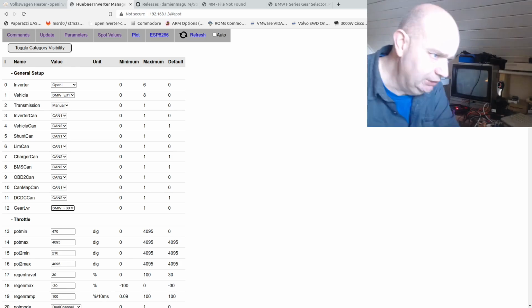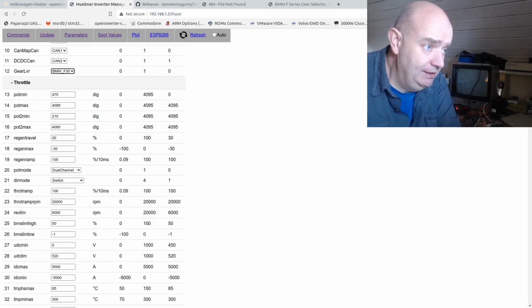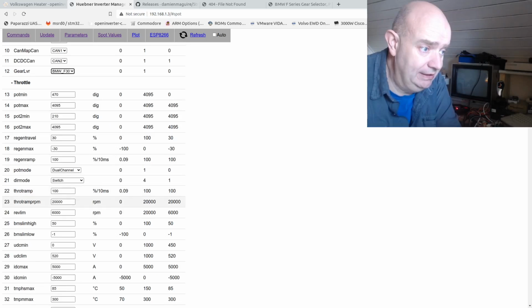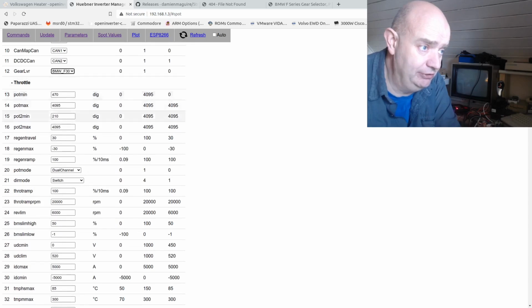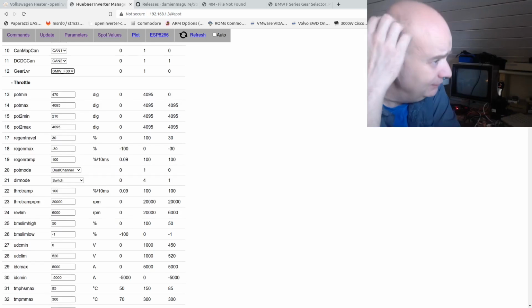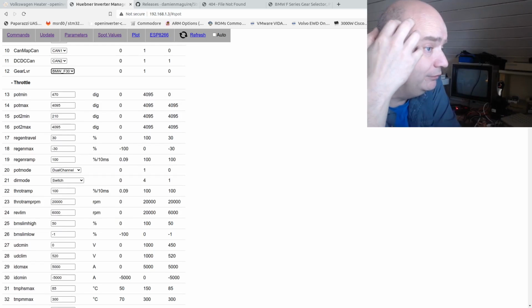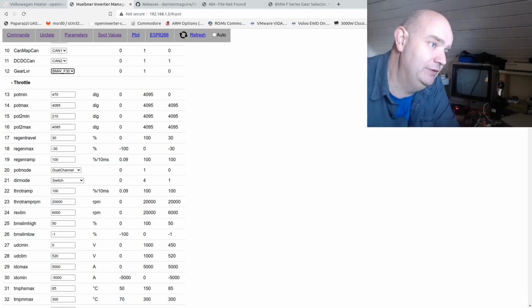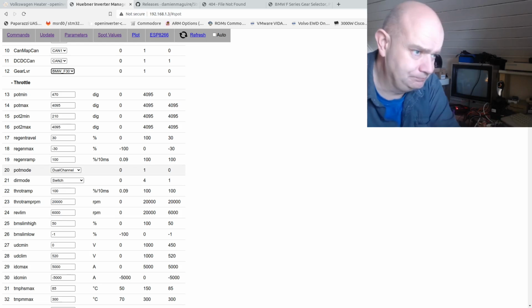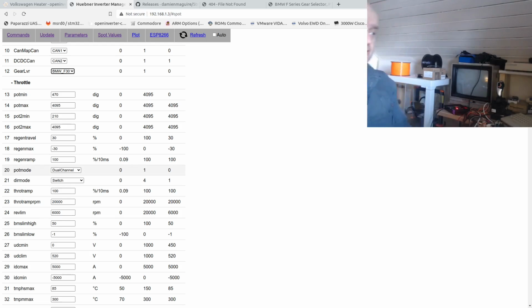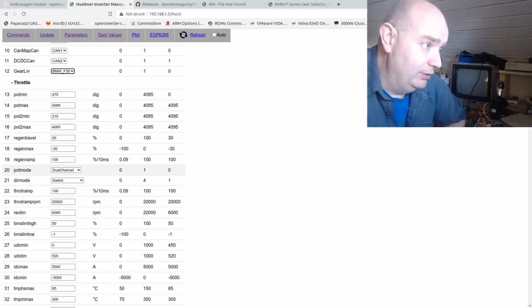So, all right, things here in Throttle are the same. There's nothing really changed in this area, but I'll just quickly run through it because I did hear that there was some confusion about how to configure the throttle and so on here. So basically, I would recommend to you that you always use dual channel throttle pedal. I'm not going to get into the whys and the wherefores, folks. That's a thing you can kind of look up for yourselves.